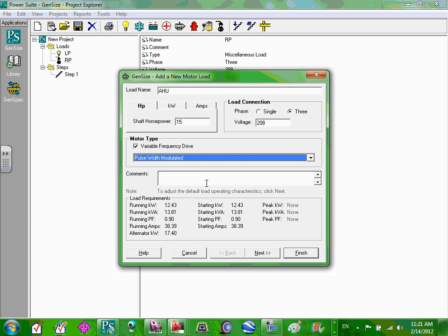So when you start slowly, gently on the motor, on the generator, it doesn't have that shock to the generator when you start this load. Very important. So if you want to have a generator size really good, VFD is a good start. Okay, everybody knows what the VFD does? It reduces the inrush. Who cares? It will make the size of your generator, believe it or not, smaller based on the inrush.